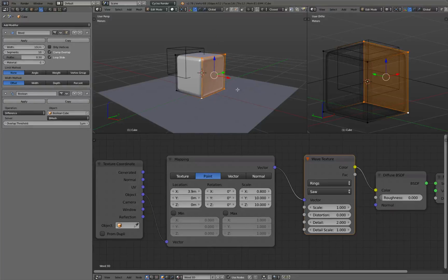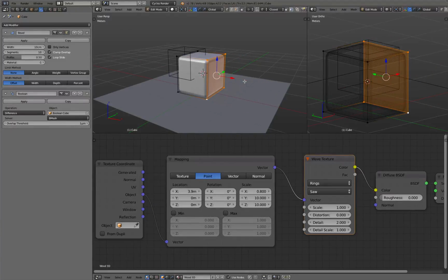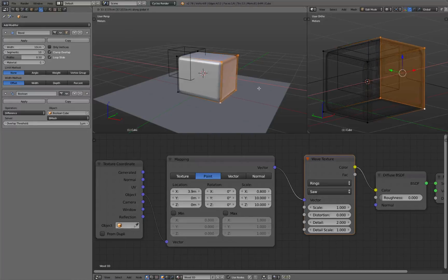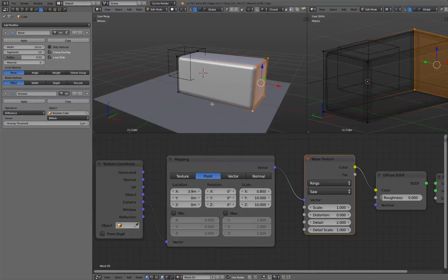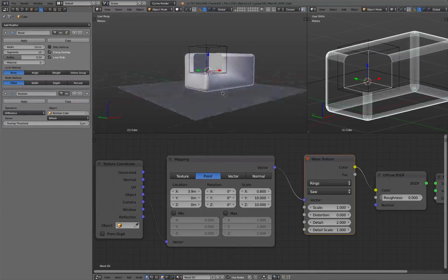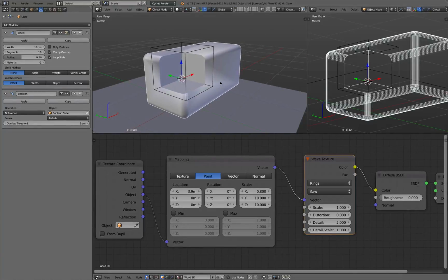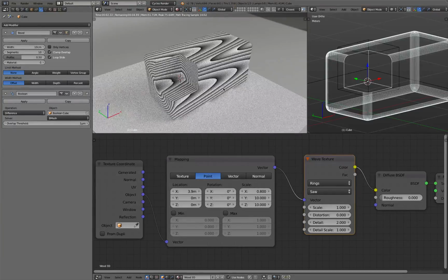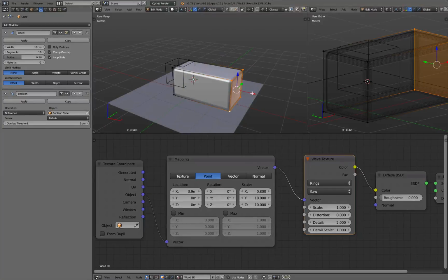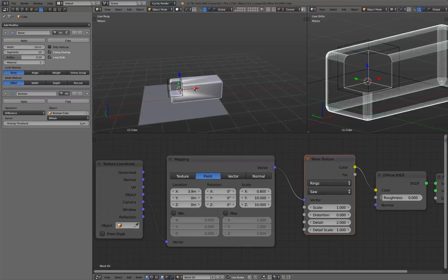So again, when you're in 3D view, just make use of the move manipulation. Or you can also press G and X, because we know we have to move it along the X-axis, move it as desired, and then click. Perfect. Now you see we have a bigger plank. That's much better. This way we have a bigger wood material we could preview, and this is still actually not very big. So those were one or two ways.